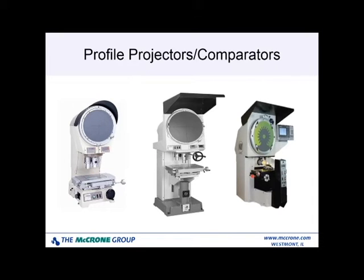On a horizontal comparator, the objectives are here at the back and look horizontally across the specimen. And like the others, the image is projected up here on the screen. Many American manufacturers have preferred horizontal comparators because they are much better at handling large, bulky, very heavy parts, and because of the heavy industry in the United States, the horizontal comparator has been a preferred instrument for measuring.